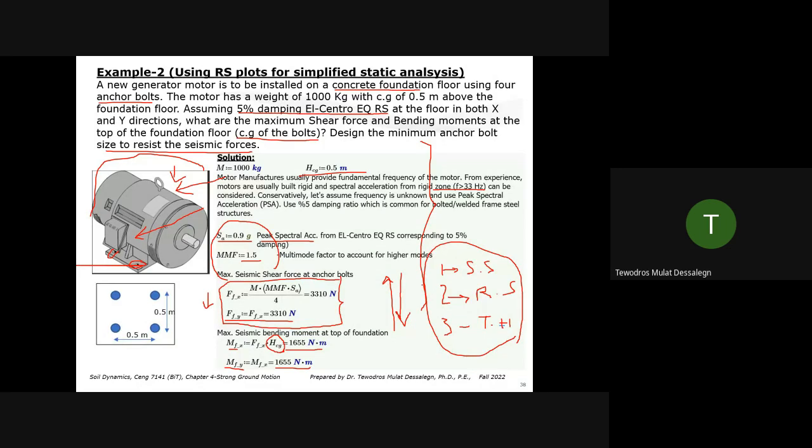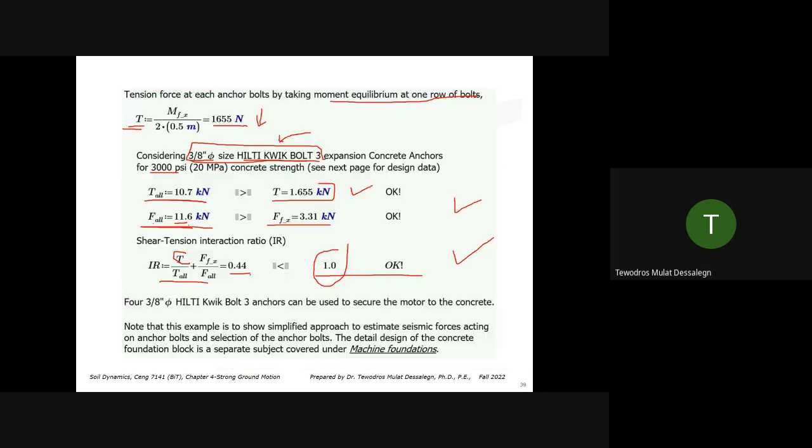If you want something more complicated, then go for response spectrum. But you'll be required to model the structure and use some software. And that same model you prepare, you can apply time history, but it's going to be time taking. So the first one, it may take you half a day to do it or a couple of hours. The second one, maybe 2-3 days, depending on the structure. The third one, maybe a week. So it gets more expensive with time, or it gets more time taking. The more fancy, the more accurate you are, it takes more time.